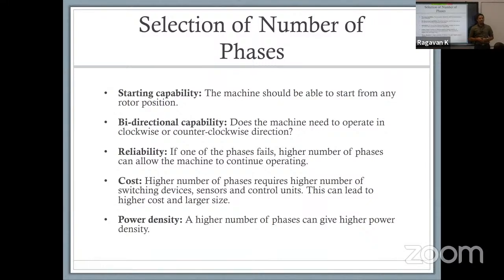You have to start looking at it. How long are they going to handle it? Do you have enough space, enough clearance for them to be air cooled or passively cooled? The cost, how much is that going to cost you? How many phases? More phases means more switches. That many coils that need to be formed increases the cost as well.